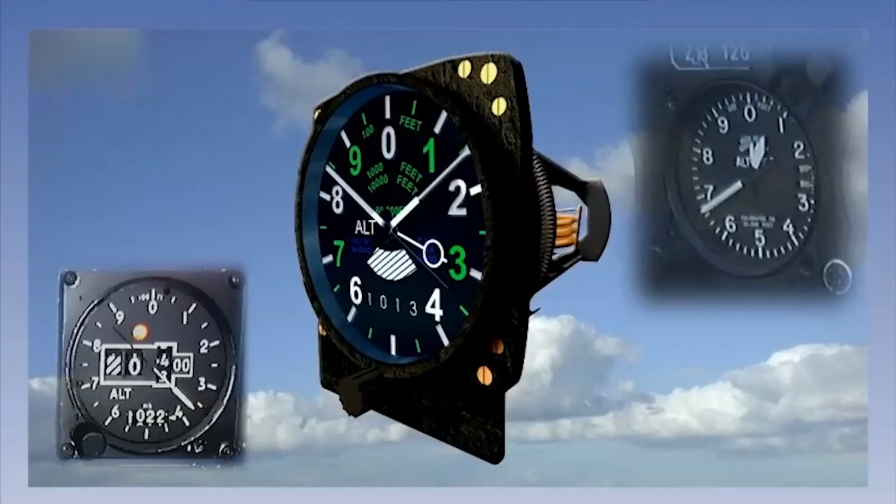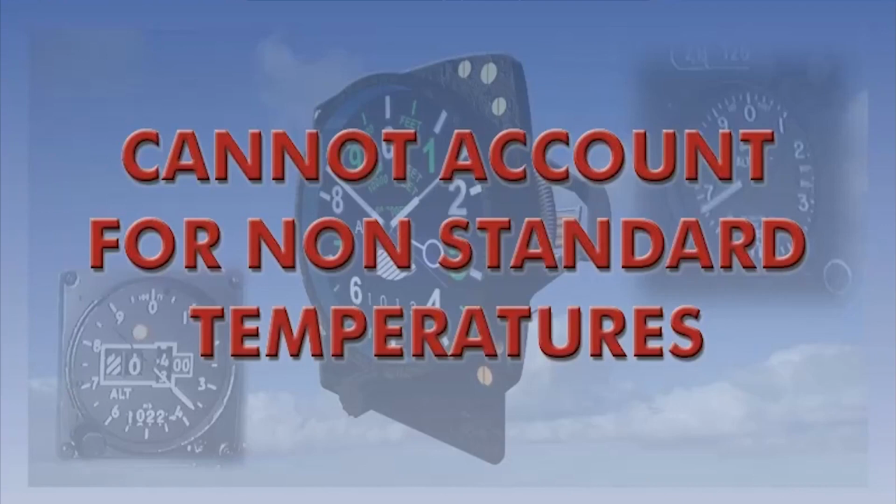So far, we've looked at how the altimeter works and how we can best use it to eliminate varying pressure changes along a route and near the ground. The variable subscale and the different pressure settings helped us to do this. However, there is one significant variable which the altimeter cannot cater for: temperature.